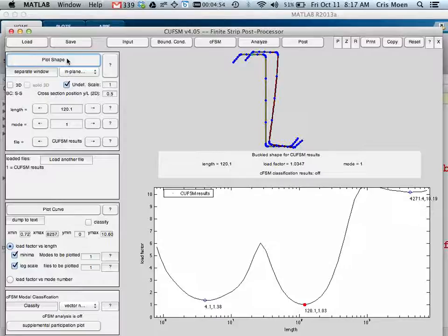But something else that's super cool here is that usually for lateral torsional buckling, you have one long half wave, so that deforms along the full span, right? But when you add a spring, now it's like a column on an elastic foundation, and you can get multiple half waves even for lateral torsional buckling. So the half wavelength for lateral torsional buckling is 120 inches. So that's 10 feet. So how many lateral torsional buckling half waves will you have in your purlin if our span is 25 feet?